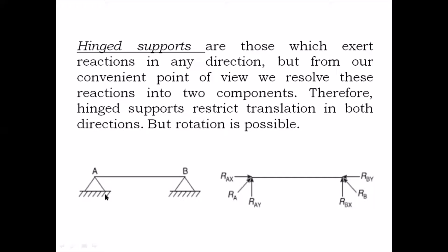and you will have some small lines at the bottom. Now what you need to keep in mind is hinged support always has two reactions. Which are those two reactions? One in vertical direction, one in horizontal direction.